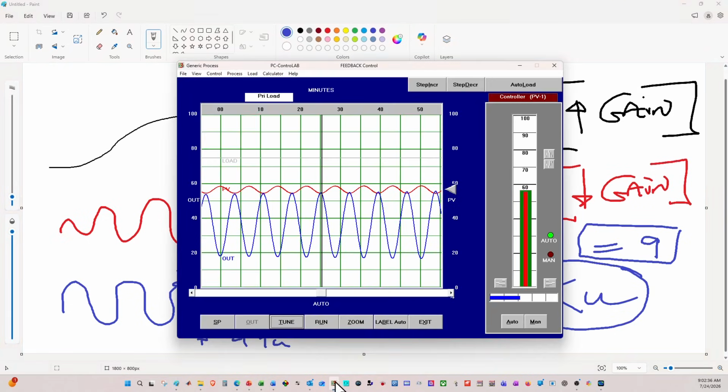Getting back to my simulator, you can see that my time scale is in minutes. And if you look from the left to the right, 0, 5, 10, 15, 20, 25, 30, every block is going to be about 5 minutes. Now maybe we can go and grab the signal from that point over there. It looks like 5, maybe 7.5 minutes. Would you agree with that? It's going to be a complete block and another half a block. So I can get a PU period of about 7.5 minutes.